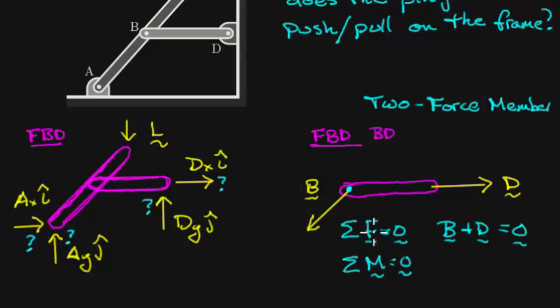And then likewise, since I need my forces to add up to 0, the force at pin joint B would have to go the exact opposite way. So in other words, these two forces would have to be collinear, right? Acting along the exact same line. And they can be collinear as I've drawn them, sort of pulling this rod apart, making this rod in tension. That's perfectly fine. That would create a 0 net force and a 0 net moment. Or of course, for a 2-force body, they can also go directly inward as well. But the important point is that these 2 forces have to act through those endpoints on the body. They have to be collinear.